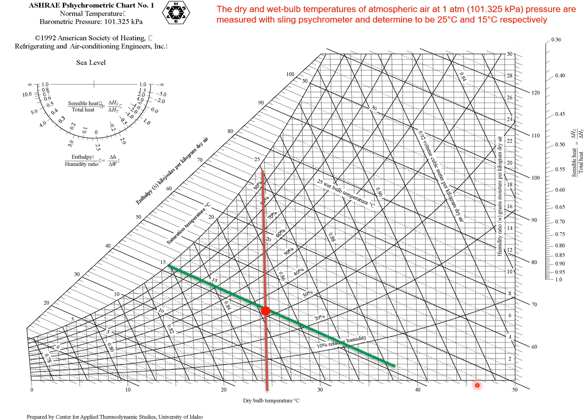What you need to do is from this intersection point, you need to extrapolate a straight line that intersects with this axis in order to obtain your humidity ratio. So you draw a line, so it intersects at this point, you read what is the value here, and that becomes your specific humidity value, right? So the next point that we want to find is your enthalpy.